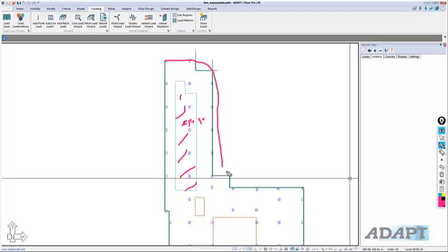The loading is cumulative, so within this zone right here, I have 25 plus 50, because that 50 live load wraps around the entire slab. So here we have a total of 75 in this region. You can also add negative loads to offset loads in the program.